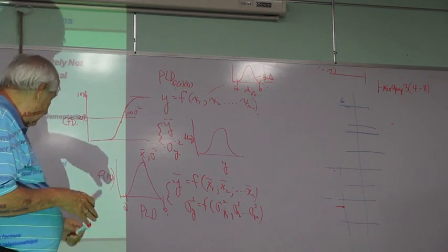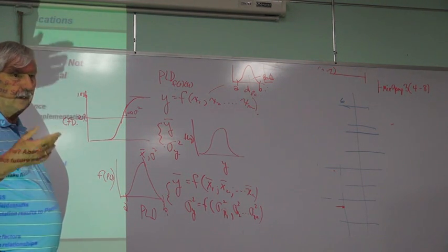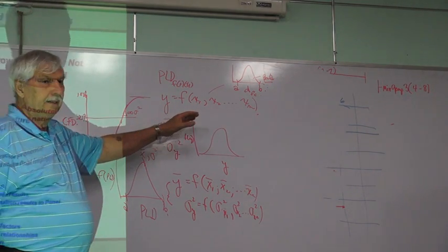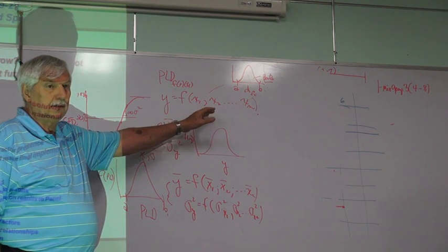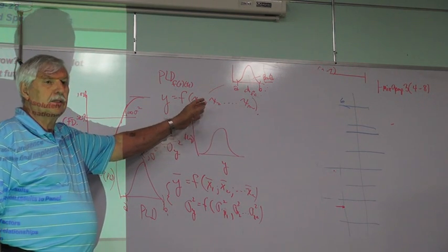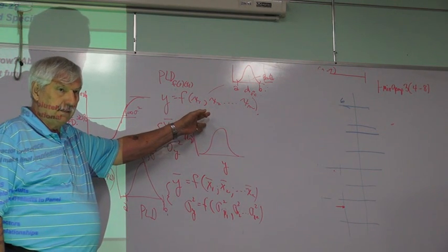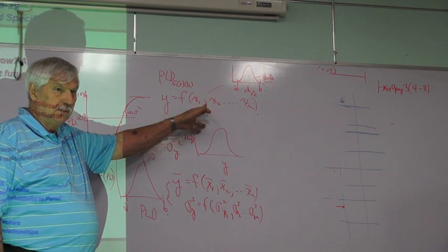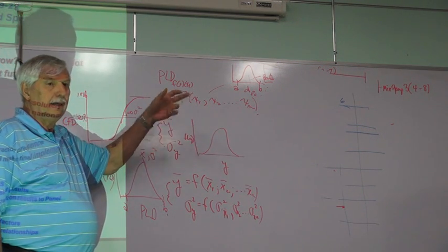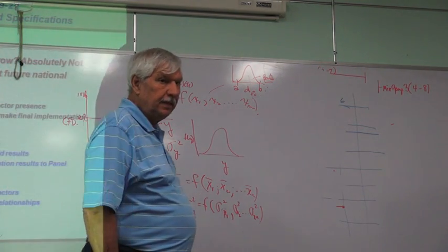Again, it's a complicated process of closed form solutions, but all of this has been done by first building a closed form solution for predicting fatigue damage, then inverting that to find what the pure damage is. Then what is going to be the total damage by taking into account the actual traffic? And then once I have the total damage, I can calculate the predicted life difference. So that's the concept that's used.